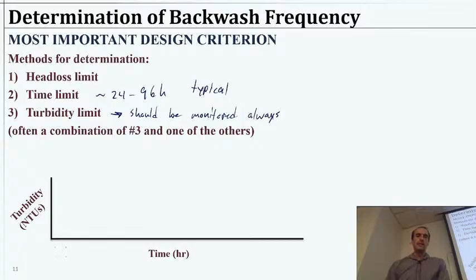So let's take a look then. What would the turbidity look like if we are starting a new cycle? Like I told you before, the beginning is some ripening. Sometimes you might call it rinsing. Since you can't read that handwriting there anyway, it's not very good, I'll just redraw it. So ripening or rinsing for the first little bit right here.